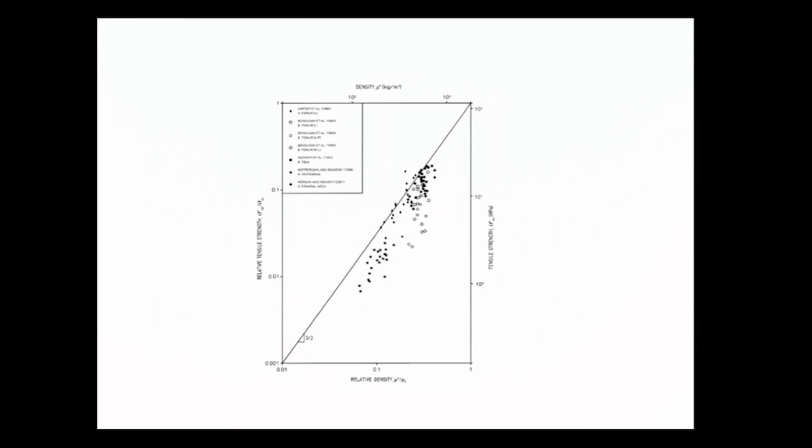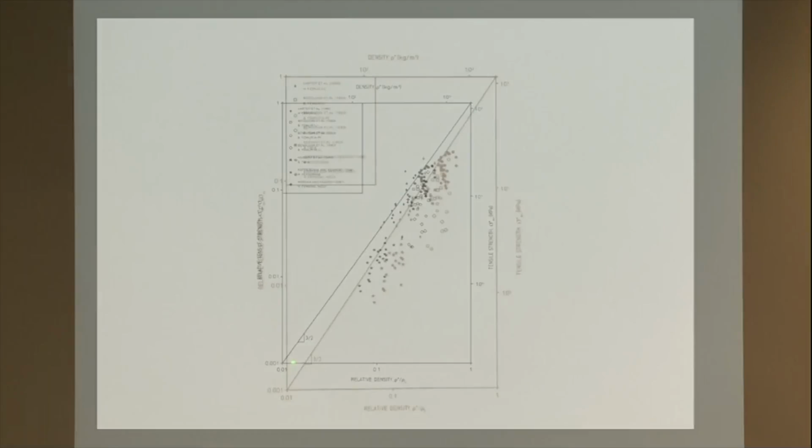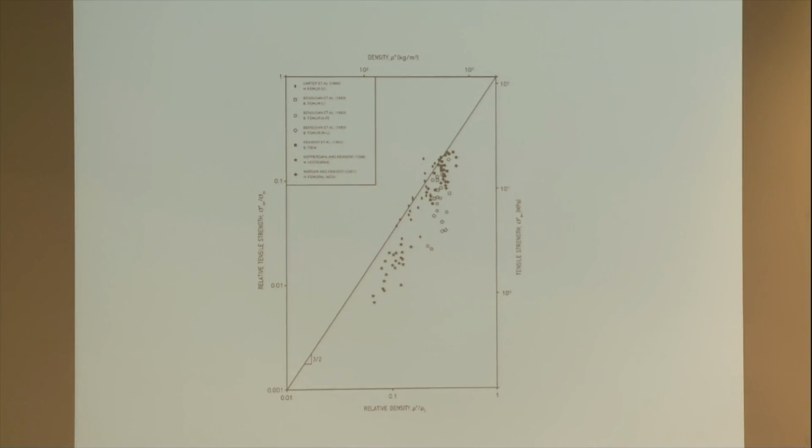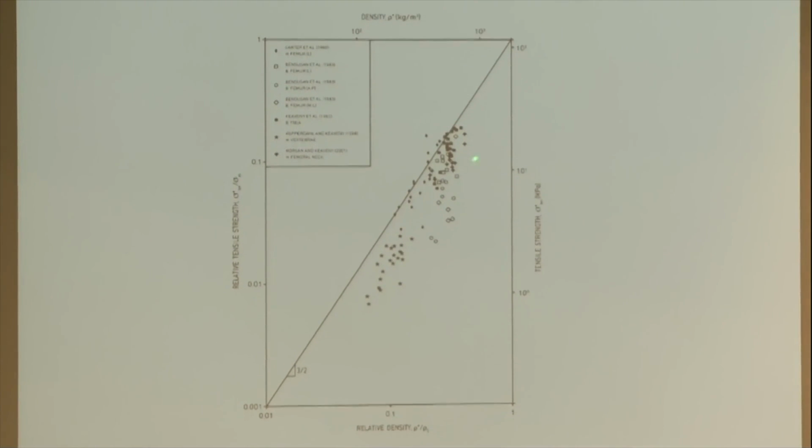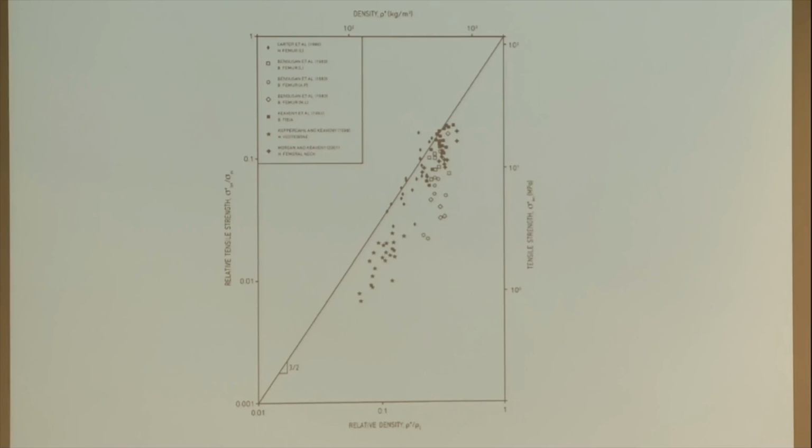This is the tensile strength. If you pulled the bone in tension, you wouldn't expect to get buckling, you'd expect to get plastic yielding. And if you got yielding and you used the open cell foam model, you'd expect a slope of 3/2, so this line has a slope of 3/2. And this line is towards the upper bound of that set of data. You could imagine a line that went through it a little bit lower, but the same slope.